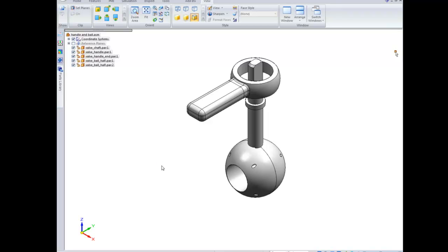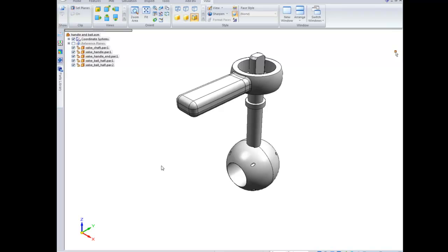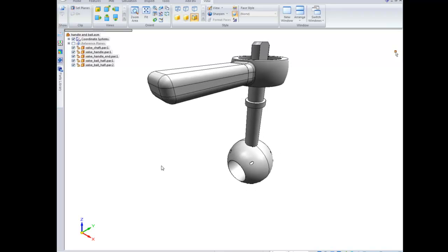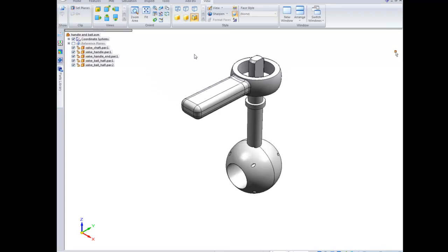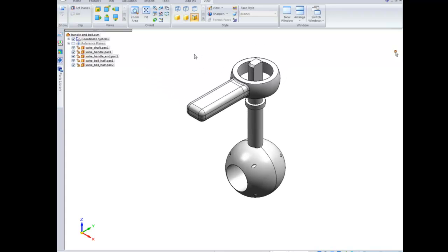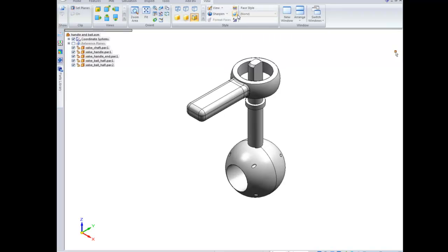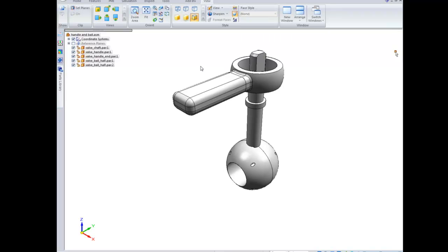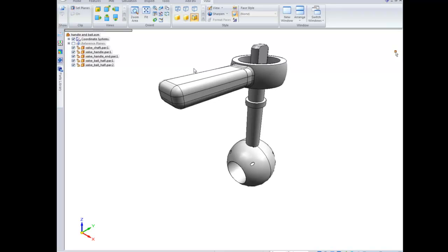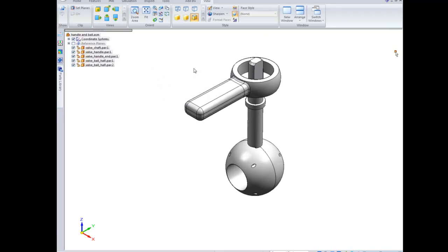We can also show you the perspective. So if we hold Control-Shift and then just start moving my scroll wheel, it slowly adds perspective for us. You can see here our perspective came on. So we scroll back down all the way, it'll turn back off. So let's say you scroll halfway, and then you want to turn perspective off. If you turn it back on, it'll go right to where you left it. So you can add as much perspective as you want. That's a quick way to do it.